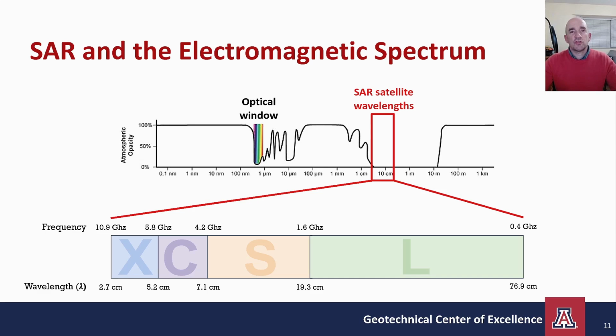So why not just use one wavelength? Well, the shorter wavelengths offer higher sensitivity to displacement, but as a trade-off, they also offer higher sensitivity to unwanted effects from things like the atmosphere and from vegetation. So if you're monitoring in a vegetated area, you are forced to opt for a longer wavelength sensor to get any results at all, because shorter wavelengths are scattered unpredictably.